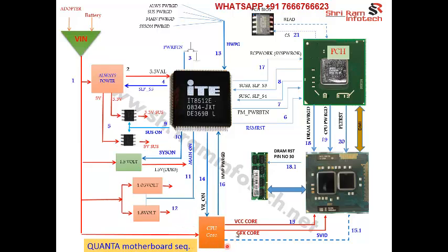And once the voltage is stabilized, the VRM section generates the next signal, which is called IMVP power good. The IMVP power good means the VRM section is okay, the VRM section is working fine. That is called IMVP power good, which means all sections are okay.